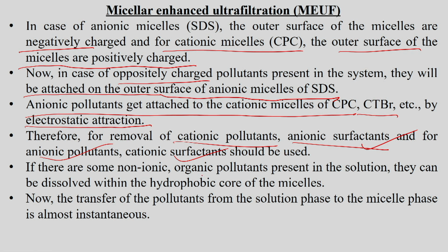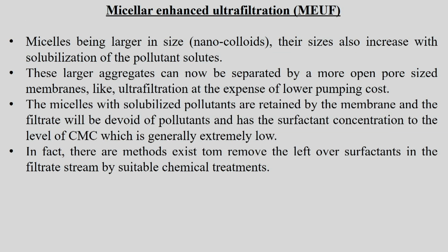Okay. If there are some non-ionic organic pollutants present in the solution, they can be dissolved within the hydrophobic core of the micelle also. Some hydrocarbons are also trapped inside the core of the micelle. The transfer of the pollutants from the solution phase to the micelle phase is almost instantaneous. Micelles being larger in size, their sizes also increase with solubilization of the pollutant solutes. These larger agglomerates can now be separated by more open pore size membranes using ultrafiltration. That is the beauty of this system.